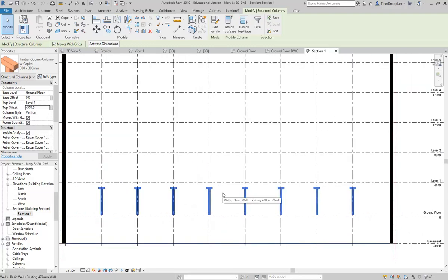Right, so that's the first part, but don't deselect them. Make sure they're still selected, so they should all be blue to do the next part. Top offset, so that means they're not selected. So just right click, and then select all instances again in entire project, and then you'll get the top offset. Yeah, minus 570.